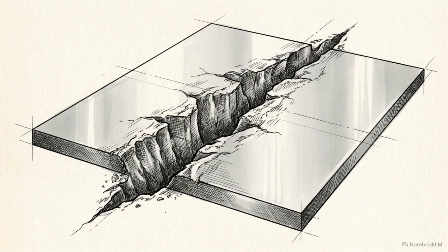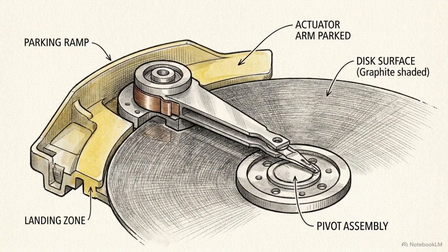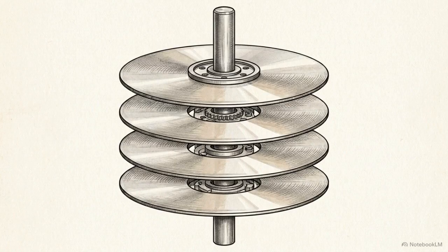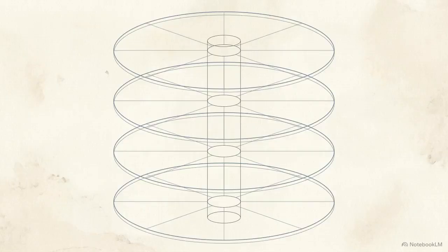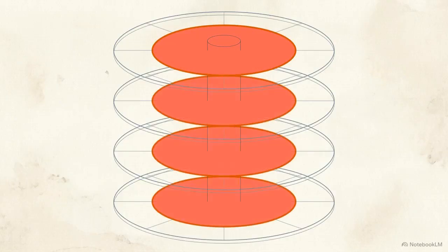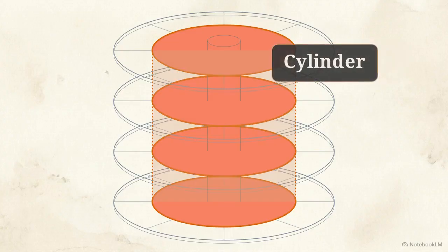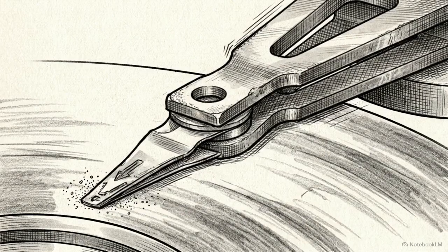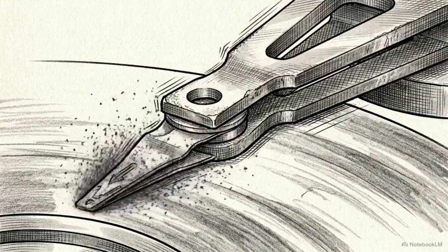If power is abruptly interrupted, the head can drop and physically scar the magnetic surface. To prevent this, drives employ an auto-parking routine to quickly retract the heads to a safe landing zone. Modern enclosures stack multiple platters on a single spindle. A vertical column of aligned tracks across the top and bottom of every platter is grouped into a logical unit known as a cylinder. Moving between these cylinders requires rapid physical actuation.